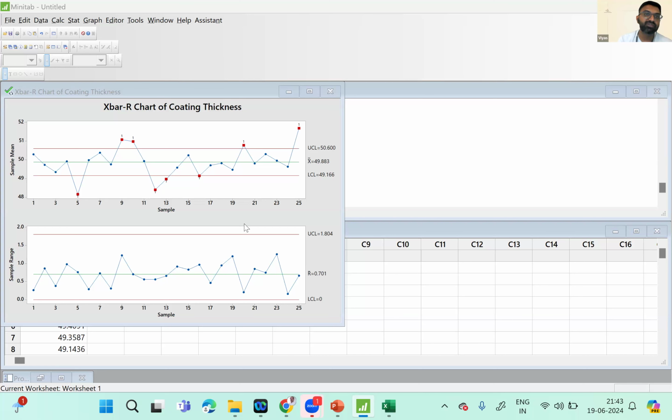Sample taken in one shift. 3 represents one complete shift. The 3 are the representative samples of all the units produced in that shift. So the variation of your parts produced within that shift is now represented by the range.